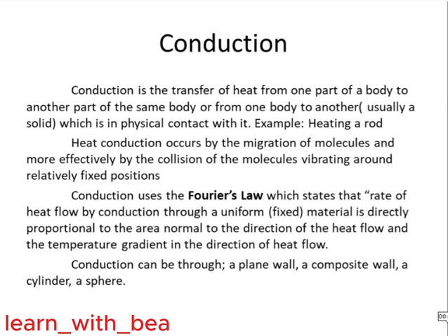Conduction uses Fourier's law, which states that the rate of heat flow through a uniform fixed material is directly proportional to the area normal to the direction of flow and the temperature gradient in the direction of flow. Conduction can take place through a plane wall, a composite wall, a sphere, or a cylinder.